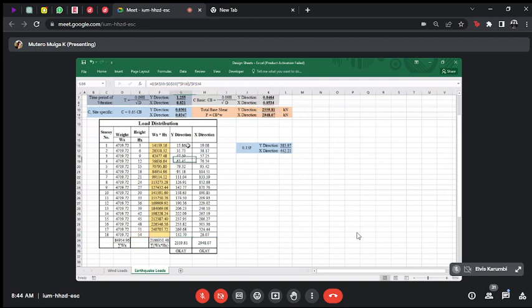Now, these other calculations for the y direction, the distribution for each floor, are based on the other formula, which takes the total force minus the force for the first floor, and then distributes it to all the floors in the x and y direction.